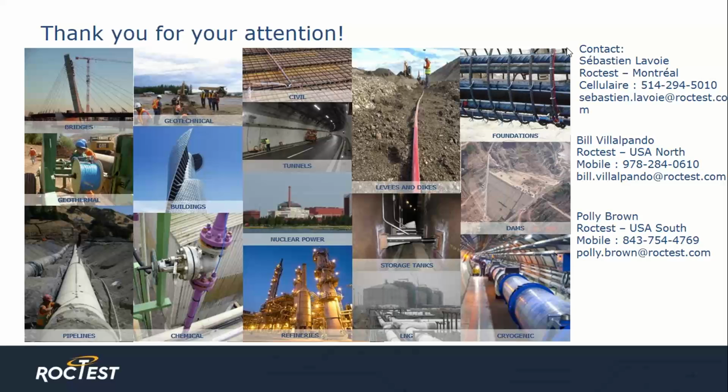Maybe one last one. Is it possible to get movements in millimeters or inches from strain measurement? Yes. When the sensing cable is buried, we typically have quantitative information on the soil movement, like the location of the event along the cable, and the evolution of the deformation as a function of time and space.